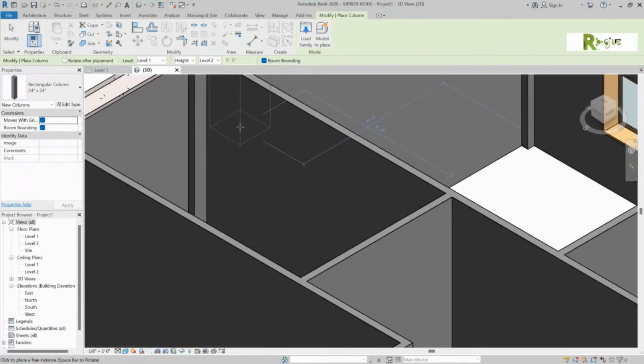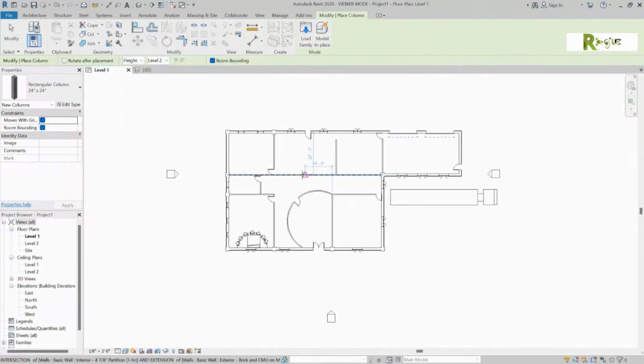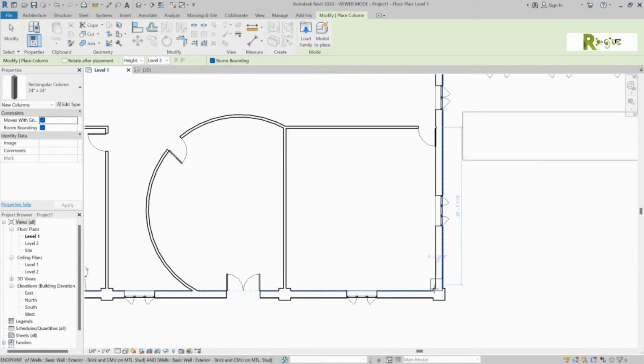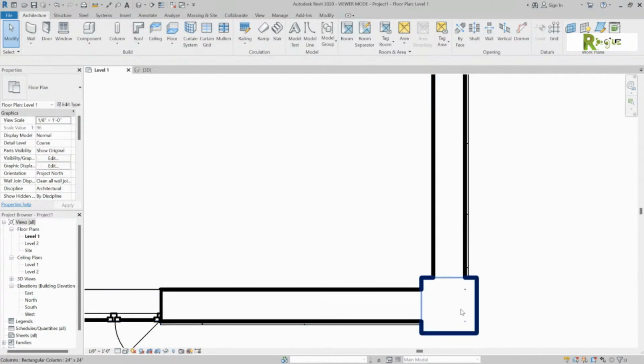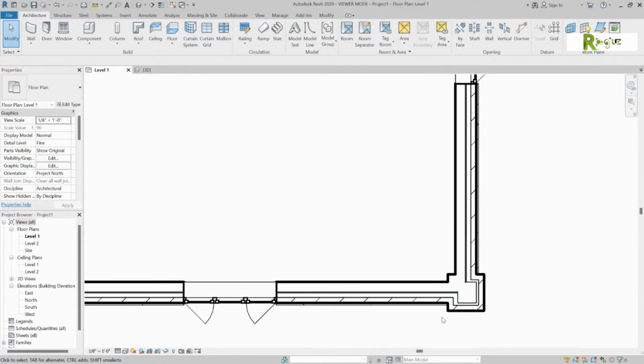If you're over in your level 1, go back to your level 1 for a second. If you zoomed in real close to that, hit double escape to get out of the place in the column command. All right, you remember where we did the box right before the shaded view? The one before the shaded view is detail level. Nope, keep it. You can keep that hidden line. That one. See, if you change this to fine, do you see how it wrapped that brick around there?